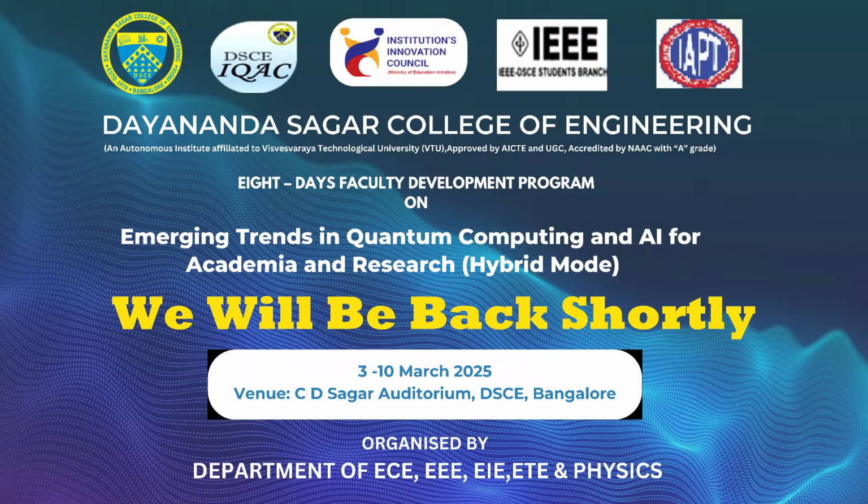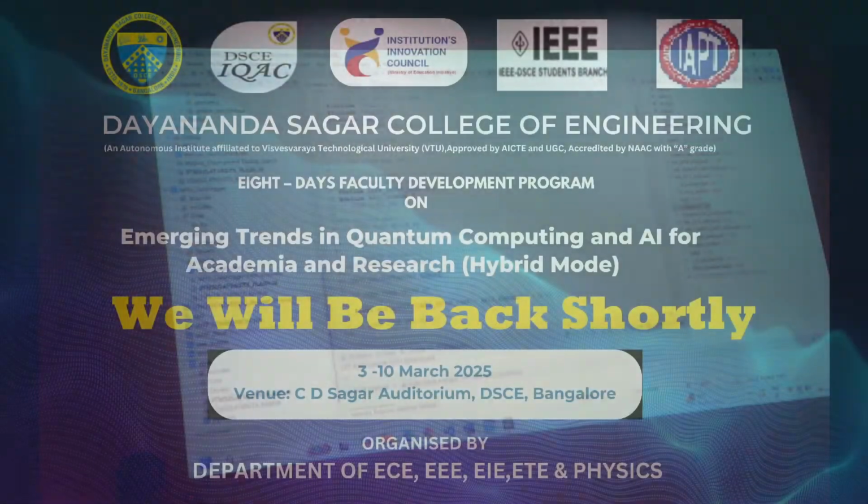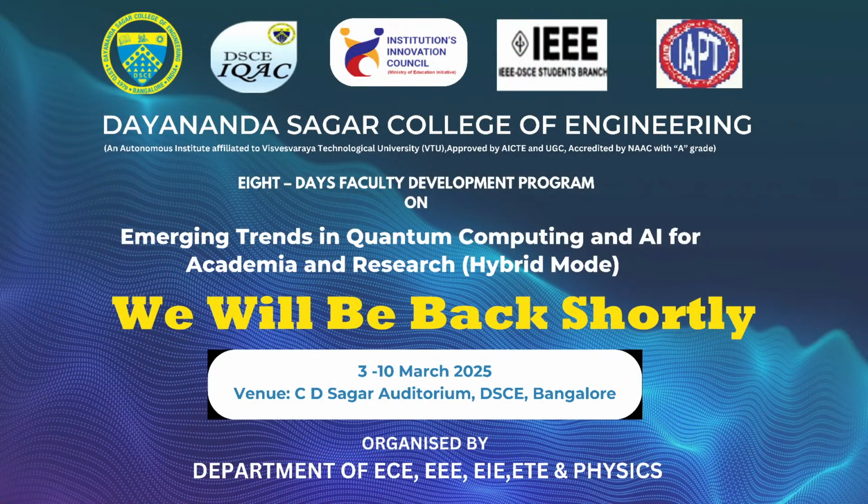Okay, if I move it, you can see the values will be changing. So the first value will be X, second value will be Y, and third value will be Z axis. Because it is a six-axis sensor, 3 for accelerometer and 3 for gyro, so XYZ values for gyro too. So these are the XYZ values continuous in a buffer size, because in Nano AI, the data comes in a buffer size. If you give 0 buffer or 1 buffer size, you can't build a model in Nano AI. What is the difference?